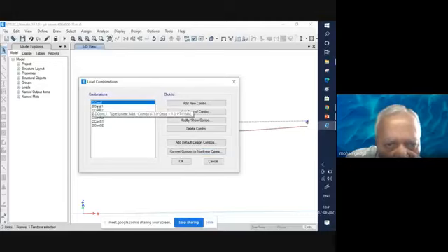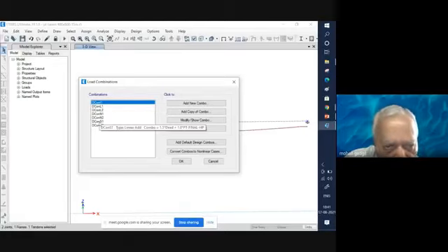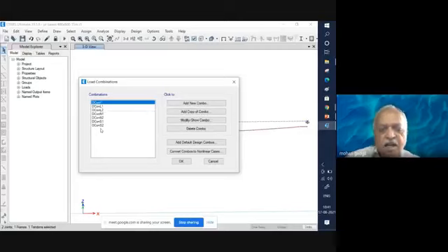Okay, now this second loading case that I have got is 1 times dead load plus 1 times PT final, and so on. The first one is dead load plus PT at transfer. The second one is PT at final. The third one and so on and so forth. So all these loading cases are generated by the software itself.